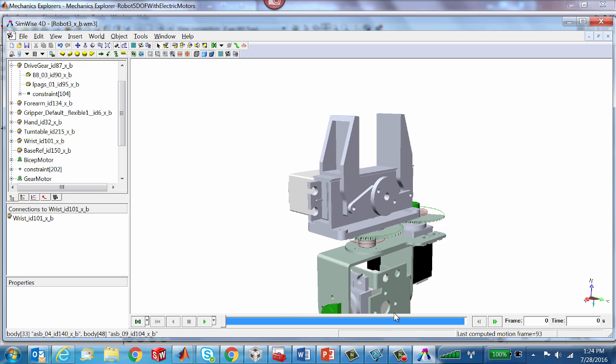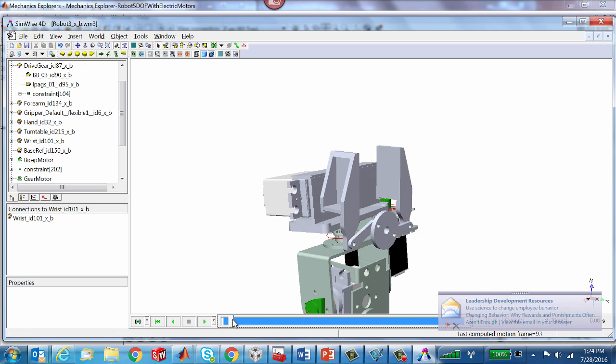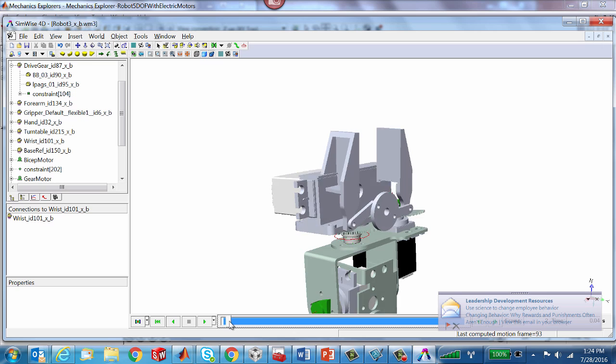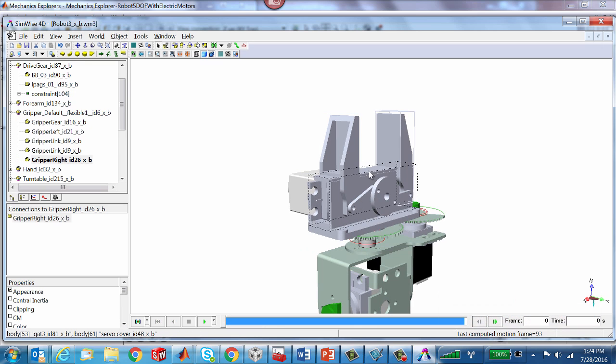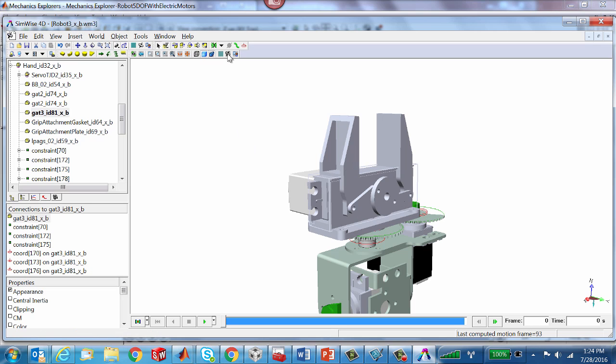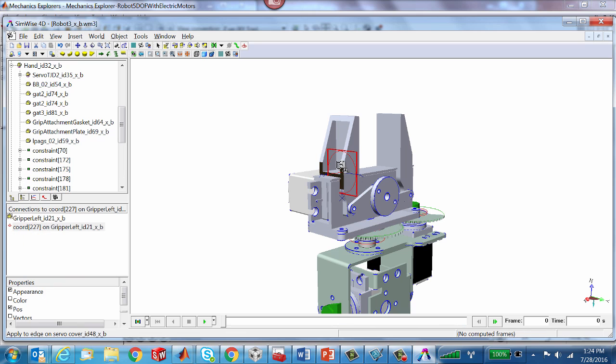Okay, so again, let's just drag this and we can see the parts that need to be attached. Basically these two grippers slide along this track right here. So we'll define a constraint type that we haven't done yet, what we'd call a slot joint or maybe a prismatic joint. When we bring it over to Simulink, it actually is called a prismatic joint. The basic idea this time is to define that directionality with the frame that we're going to allow it to slide. So I place it on this perpendicular surface.